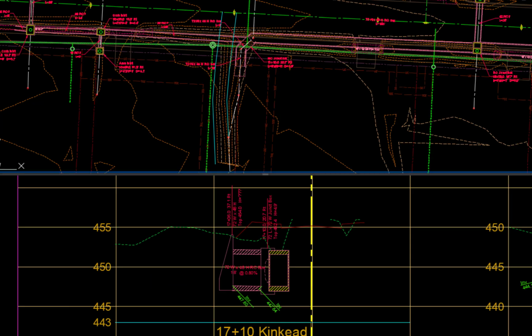Where the location of the desired profile of the ground surface is not at a uniform offset distance, a quick profile and superimposed profile need to be created. Such is the case for the pipe network at 17+10. 2 polylines have been drawn in plan view, one for the existing channel flow line and the other for the existing west top of bank.